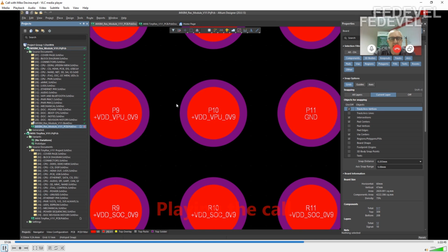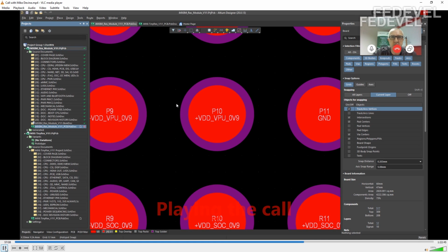And the reason for that, Robert, is that we've obviously got to register to the internal layers when we're drilling. And obviously all the material is going to stretch and shrink slightly differently. So having bigger clearances or bigger pads on all other layers, it's easier to register, because the outer layers are then registered to where the drilling is, and it's all done with laser imaging. There are no more artworks anymore. It's all done with laser imaging. And that's why on the internal layers you need to have bigger clearances, bigger pads, to allow for the registration.